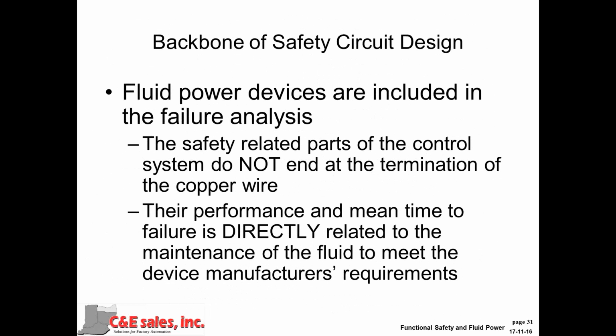Another point to remember is that the fluid power device performance and mean time to failure is directly related to the maintenance of the fluid power fluid. If the manufacturer requirements of the fluid quality are not met, there will be a negative impact certainly on the durability and the mean time to failure of those components.